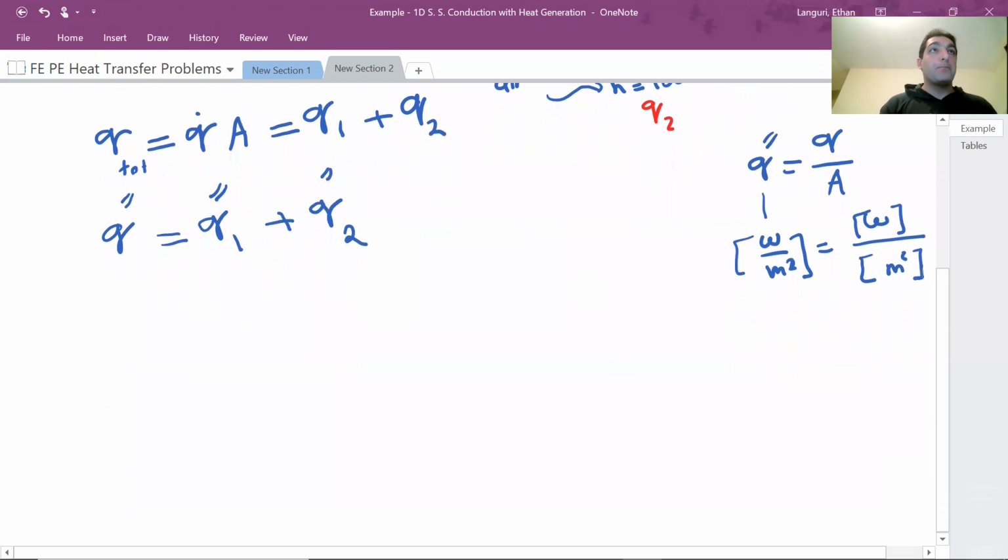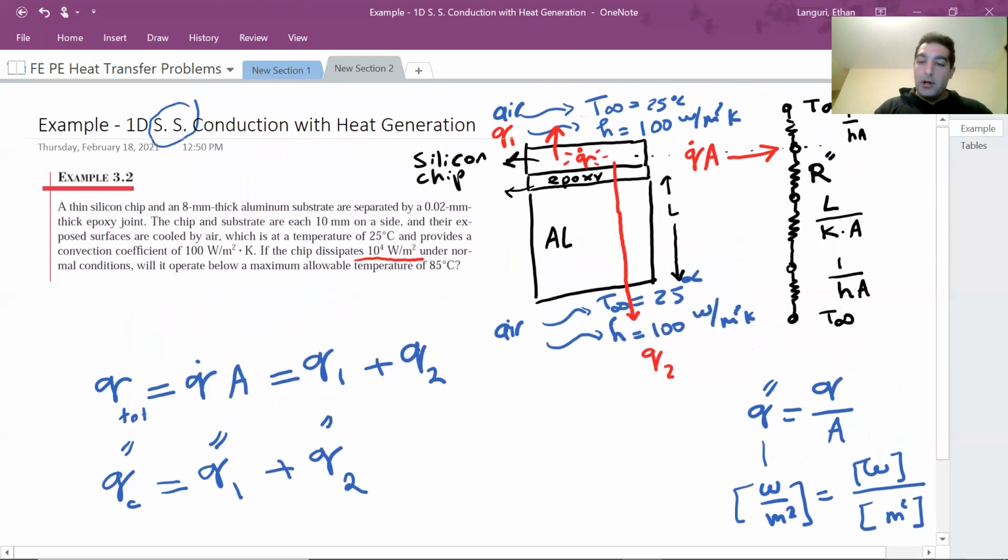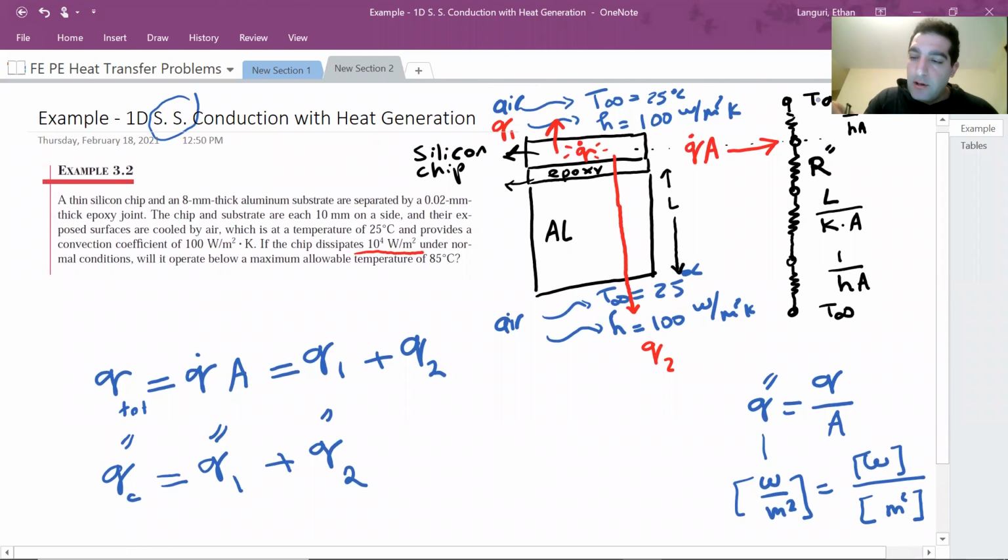So we keep going down. So let's call it the heat flux of the chip. Heat flux of the chip, I can rewrite it as the amount of heat going upward, which is nothing but temperature difference between these 2 points, chip temperature and T infinity, divided by resistance in between, right? That's the heat going to the top.